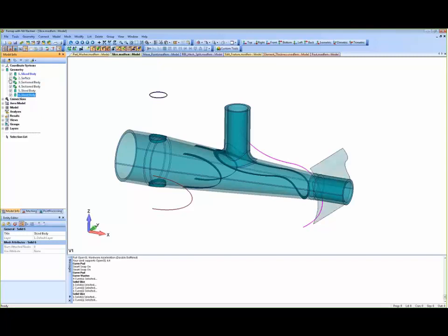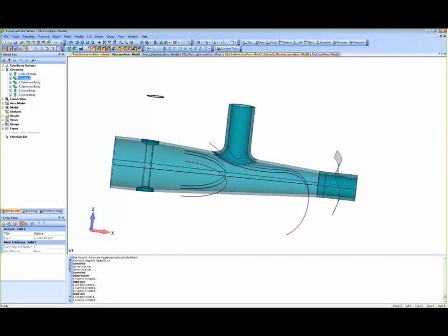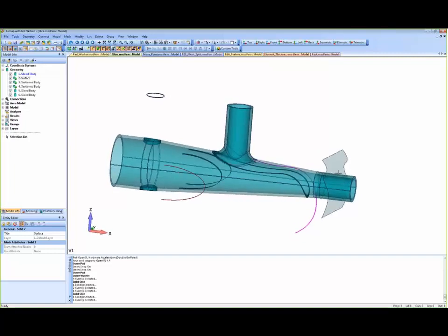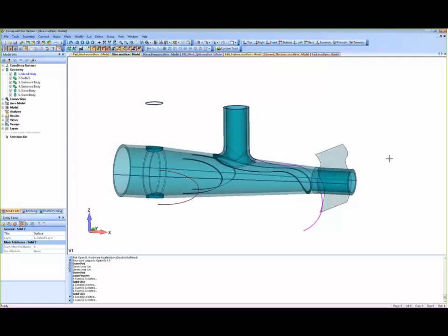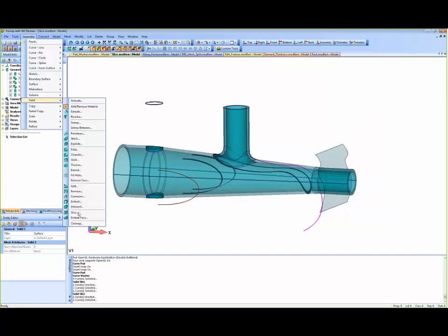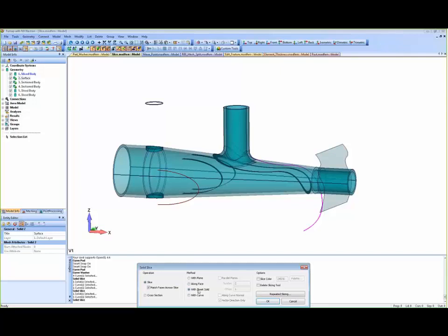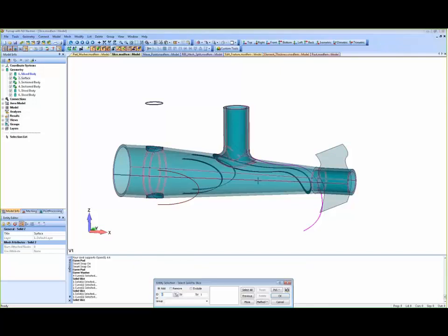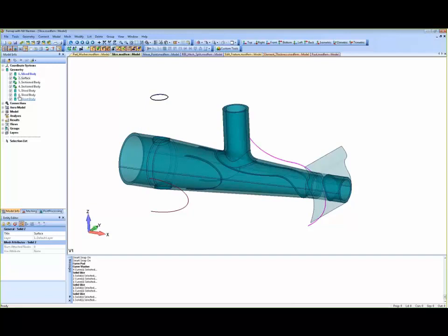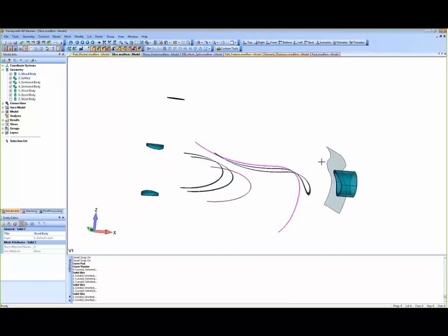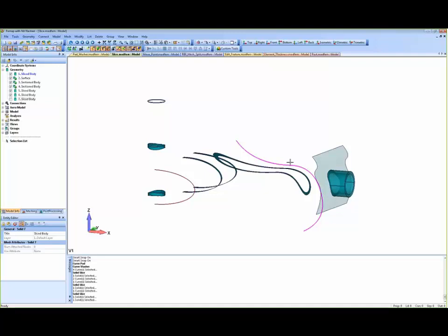Now finally, just to show you guys the last option, here I have some arbitrary surface that was made from a spline, and I moved some points around on that surface. We can do the same thing with the geometry solid slice, but we can do it with the sheet solid in this case. So again, I'm going to slice that. I'm going to use this solid here. And there we go. It created those separate bodies just from those arbitrary curves or arbitrary surfaces.